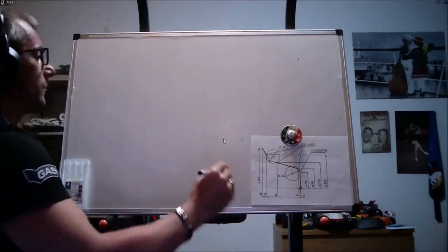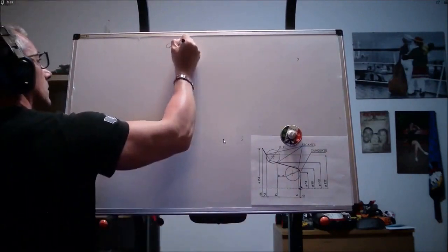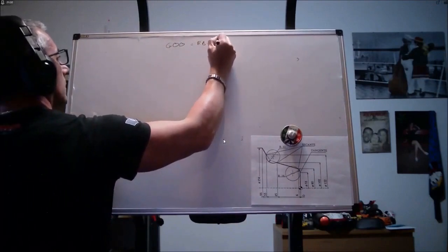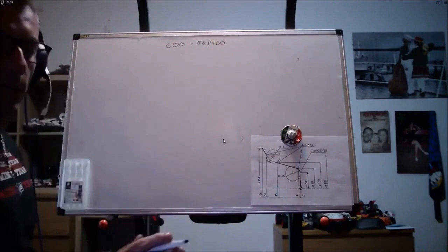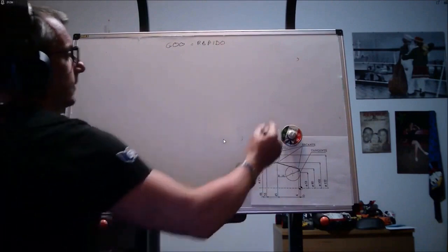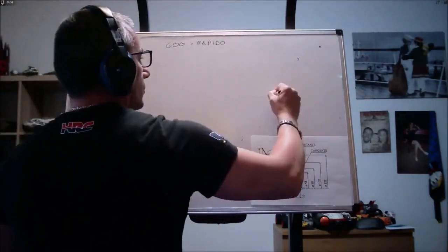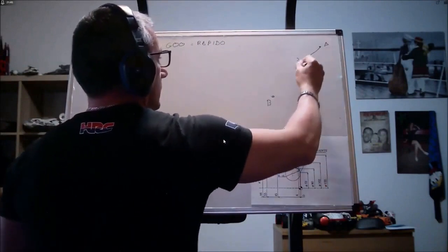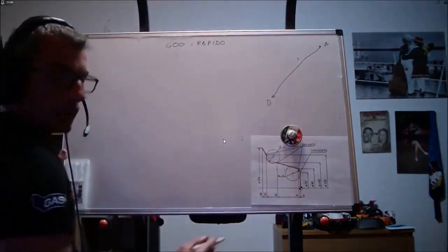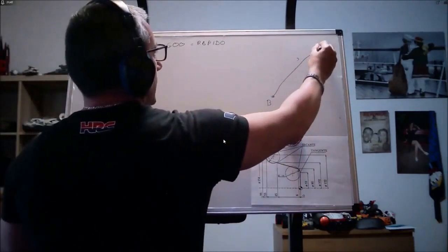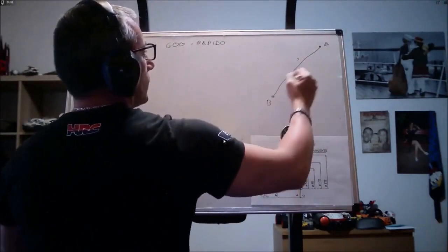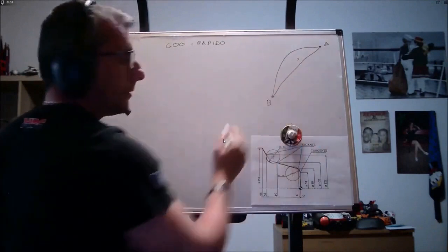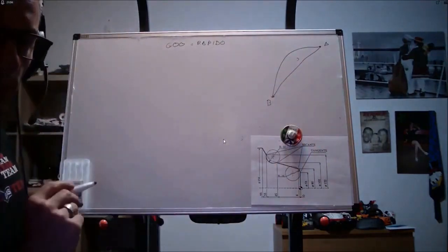So let's recap. G00 is rapid movement: some machines will execute fast movements from point A to point B along the shortest trajectory, while others will move by bringing the axes to maximum speed, and depending on whether the distance is greater in one direction or another, they may follow trajectories of this type.